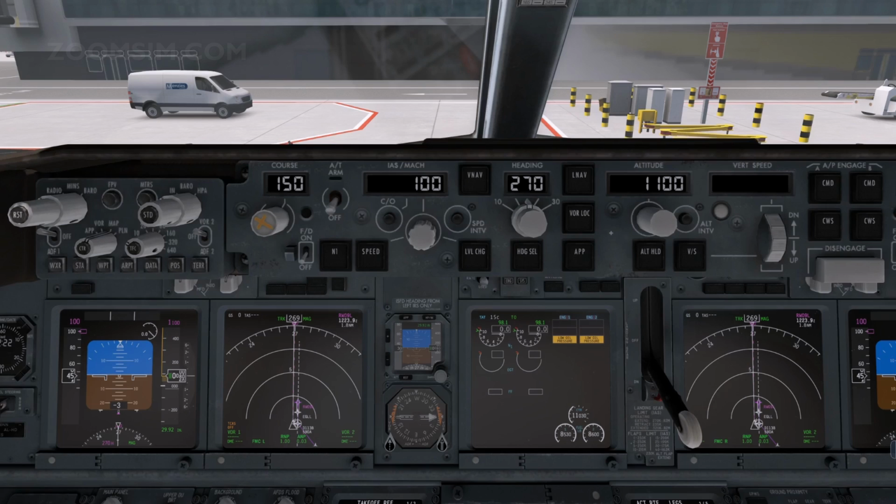And the plan position displays a non-moving true north-up route with an aircraft symbol representing its position. Route step through is allowed through the CDU legs page. Weather radar and TCAS are not displayed. Center as required. When pushed, a full compass rose is displayed for approach, VOR and map modes. Range as required. Range is displayed in nautical miles for approach, VOR, map and plan modes.